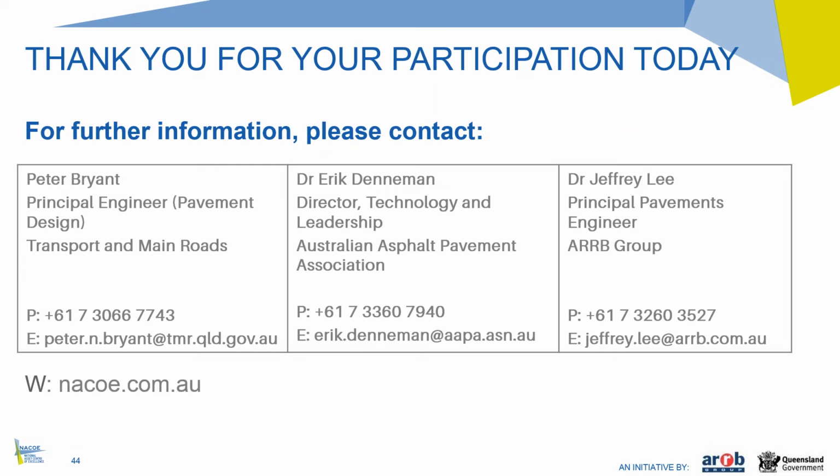We have been doing this as part of this research program, and actually the Austroads report shows very well how the modulus that is achieved in the field correlates to the modulus that's achieved in the laboratory, and that is really a function of the conditioning method that is part of the Australian design system. So laboratory specimens are conditioned to reflect what's happening in the field, and I think it's actually quite successful at doing that. That is work that must have been done many years ago when they introduced that method of conditioning. Great. So the answer is we're not going to be doing that on a large scale because we're not doing that under the current design system either.